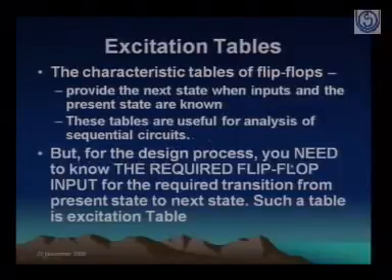For the design process, you need to know the required flip-flop input. What input should be put into the flip-flop for the required transition from present state to next state? This is very important when you are doing a counter design. What input should be given to the flip-flop so that it moves to the next state as desired by you? How you can achieve that transition from present state to next state, such a table is known as an excitation table.